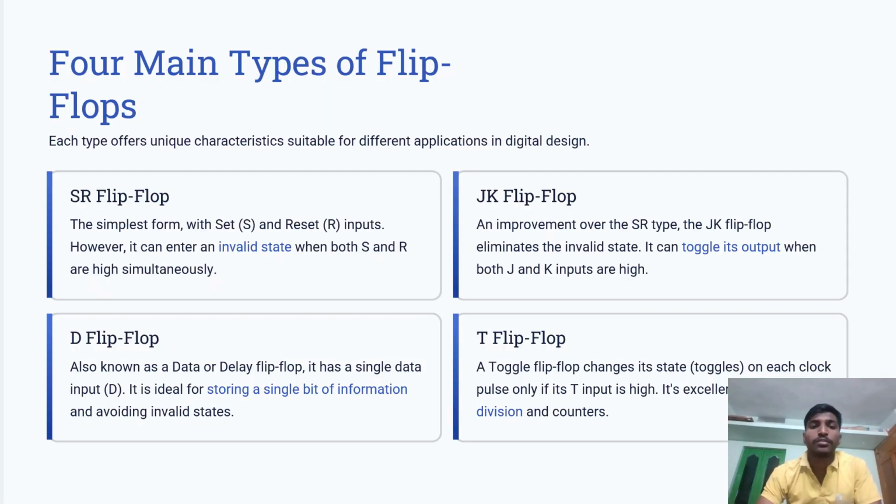Four main types of flip-flops. Each type offers unique characteristics suitable for different applications in digital design. SR flip-flop, the simplest form, with set S and reset R inputs. However, it can enter an invalid state when both S and R are high simultaneously.